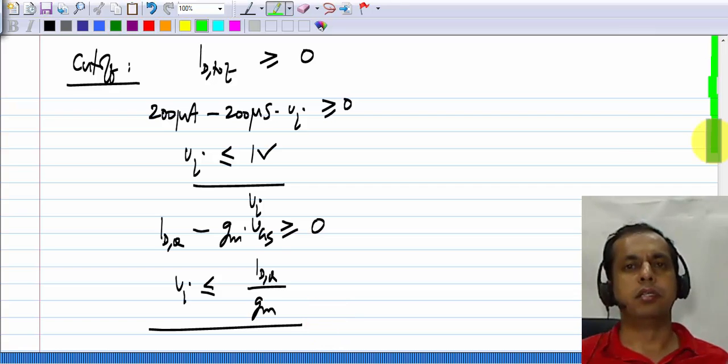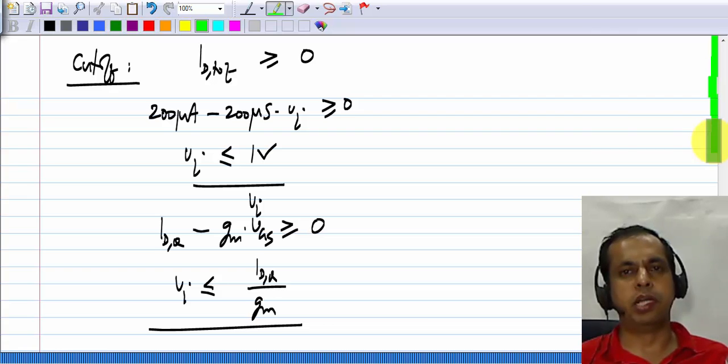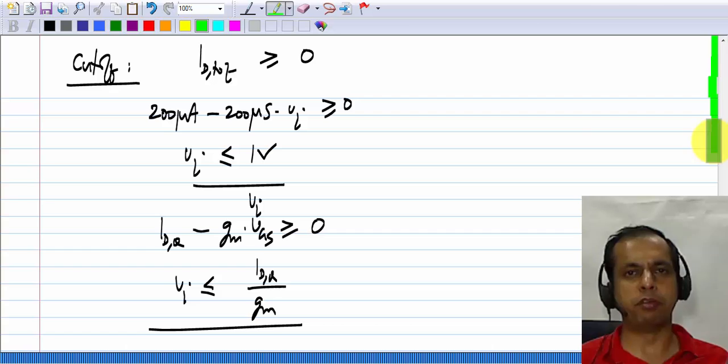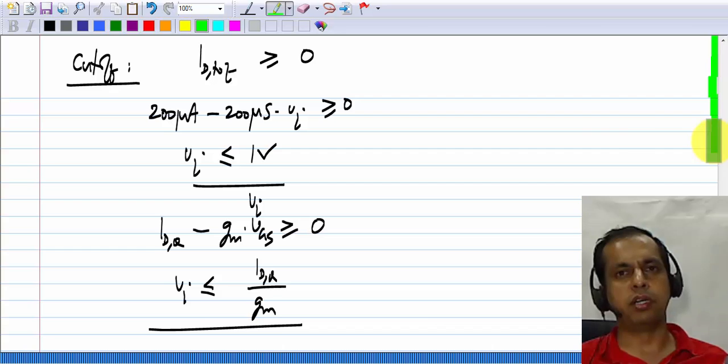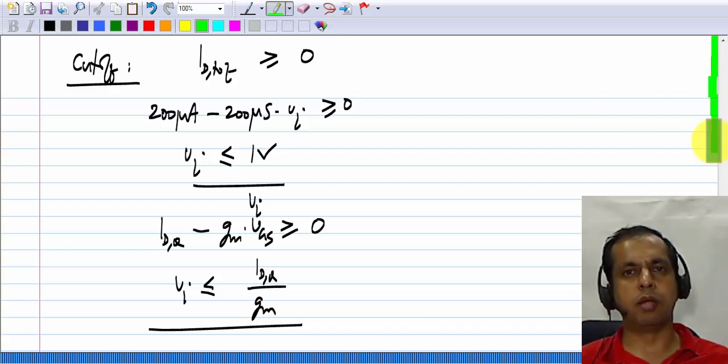In summary, the small signal picture of NMOS and PMOS common source amplifiers is the same, and this is true of every other type of amplifier. If you look at NMOS and PMOS, small signal wise they will be the same, large signal wise they will be different. Okay. The swing limits in particular are the opposite. Okay. If in some circuit saturation imposes an upper limit in the NMOS amplifier, it will impose a lower limit in the PMOS amplifier, and similarly for the cutoff. Okay.